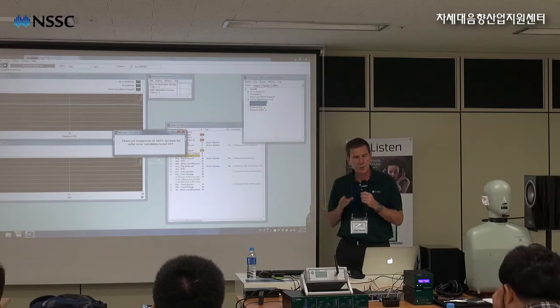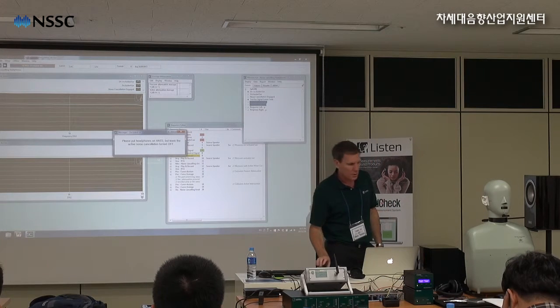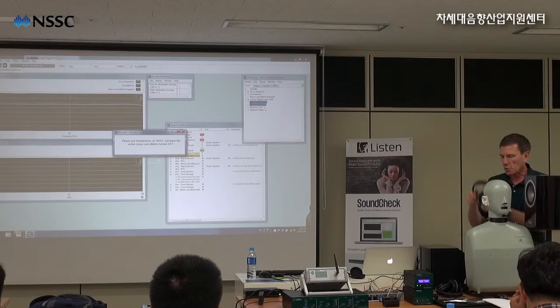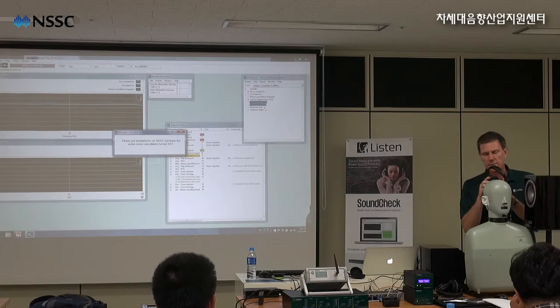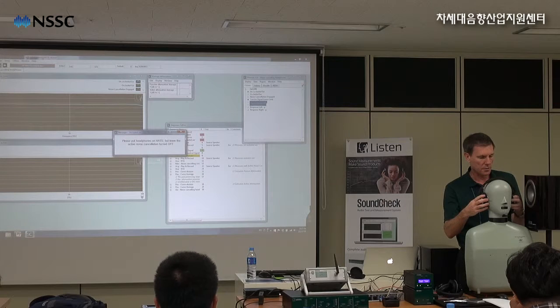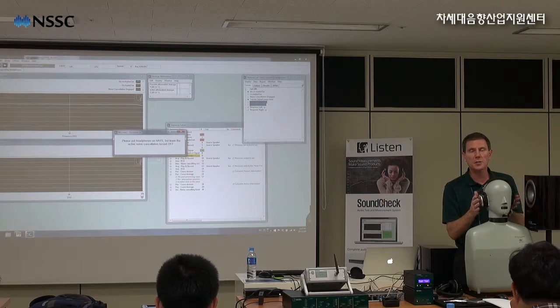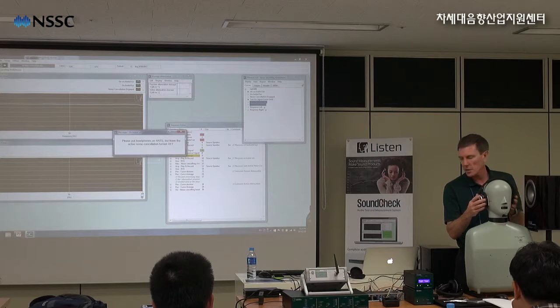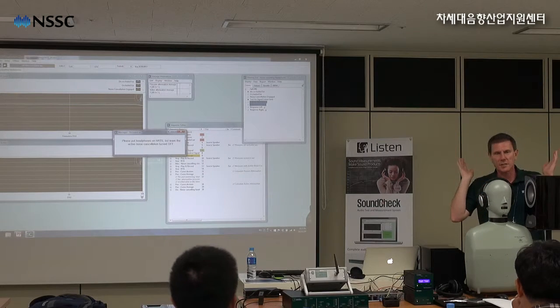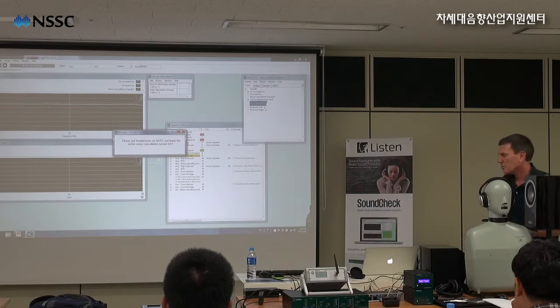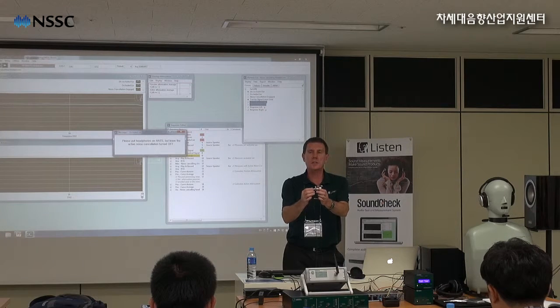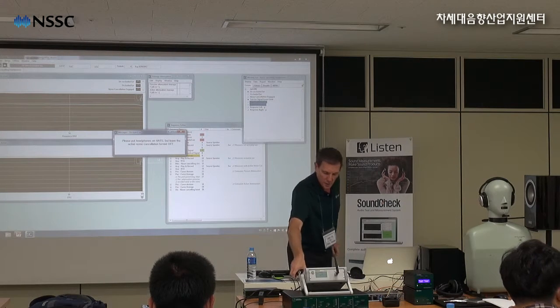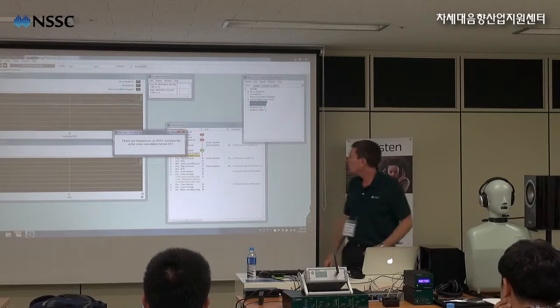So now I want to measure the passive attenuation. So no cables, just headphones. I've got the active noise cancellation circuit off, and I probably should get the channels correct. And again, the seal is going to make a big difference to how well it attenuates. If I put some earbuds in there, forget it. I'm going to get no attenuation. If I have it in the ear like this, that seals the ear canal, it's still going to give me some good attenuation. So now I just say enter.